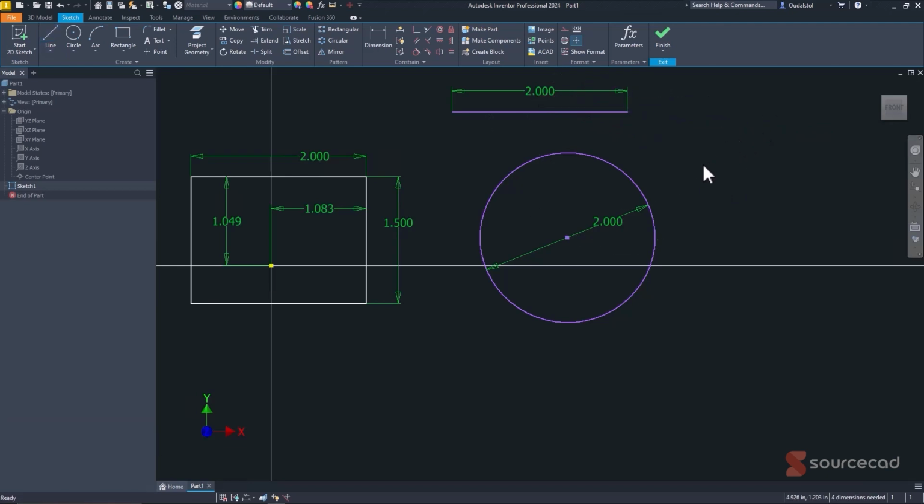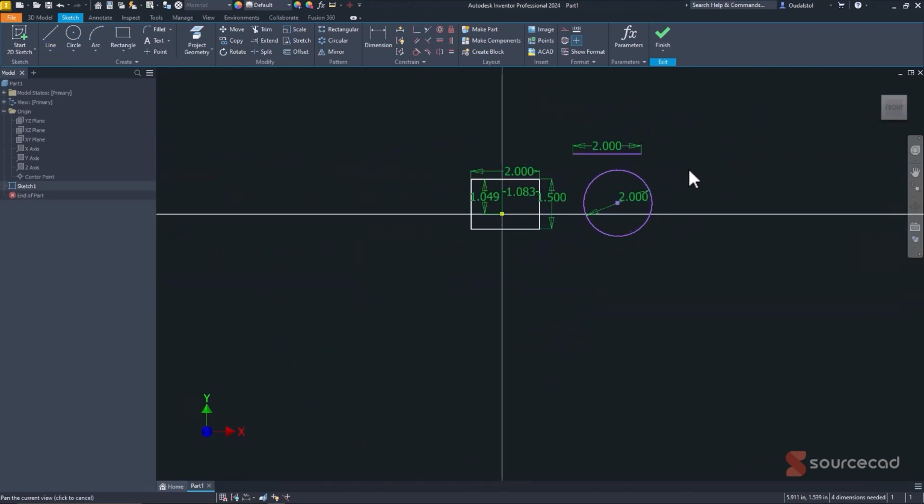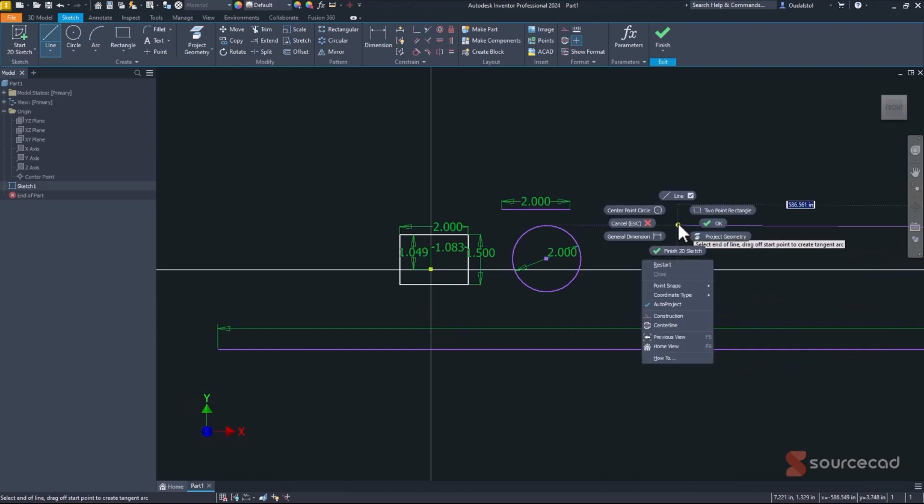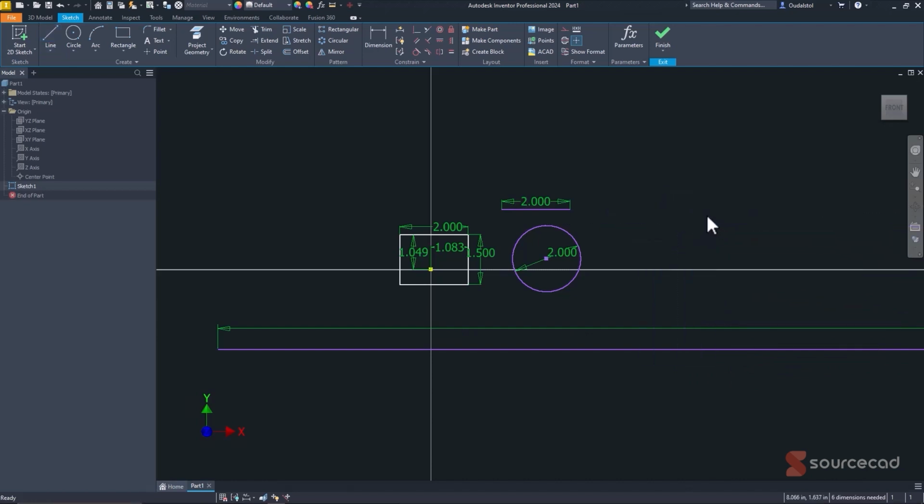And so a little trick here, because it's not always going to be zoomed into what you're going to do. So if you know you're going to draw something that's 50 feet, just to be exaggerated about it, a little trick is to actually draw a line, and 50 FT is feet. IN is inches, MM is millimeters, CM is centimeters if you want to. But if you do that, you'll get a line.